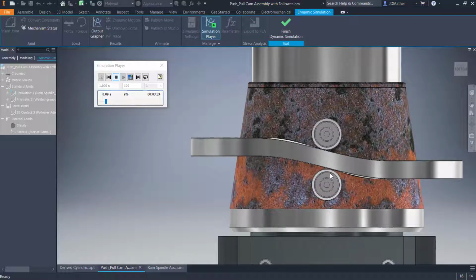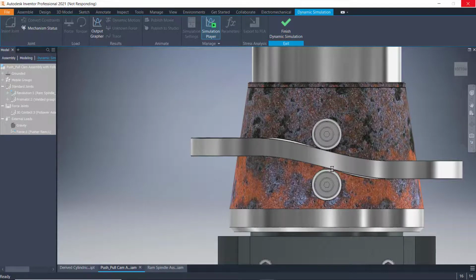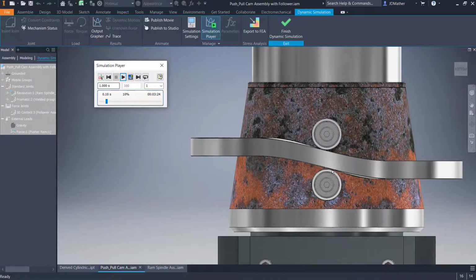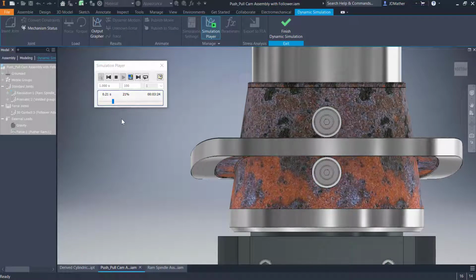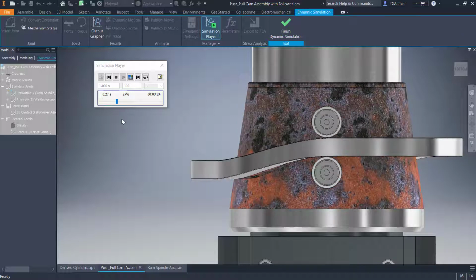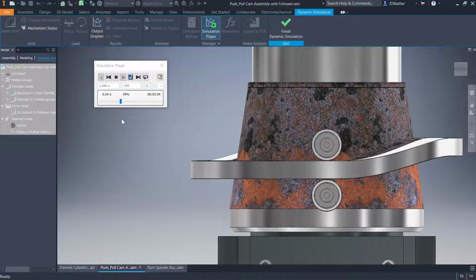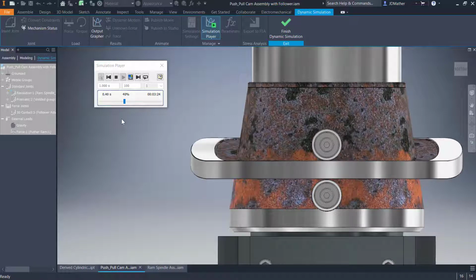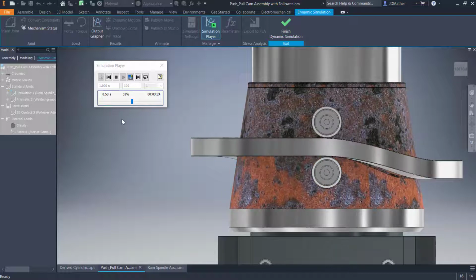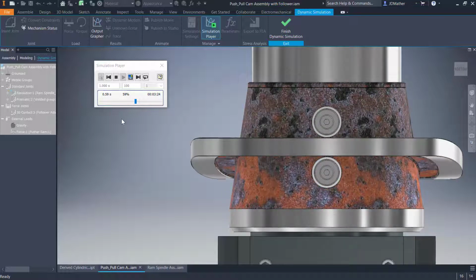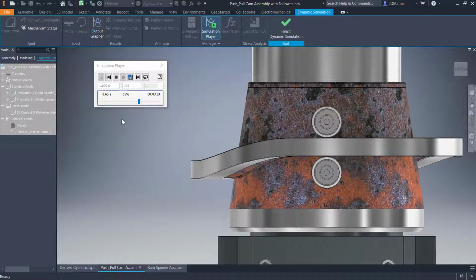So notice the tangent point on this cam is about right in here at, say, the 2 o'clock position, and then here it's about the 7 o'clock position. So that tangent location between the cams and the follower is continuously variable. It's in dwell at the upper lift, and then it begins to fall. Dwell for 120 degrees, lift for 60 degrees, dwell for 120 degrees, and then fall for 60 degrees.